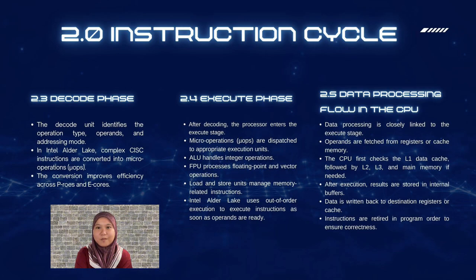After execution is complete, the resulting data is temporarily stored in internal buffers before being returned to the destination register or cache during the write back stage. Finally, the processor retires each instruction in the correct program order, committing the result to the architectural state and ensuring consistency, reliability, and correctness of program execution. This carefully coordinated data flow and execution strategy enables Intel Alder Lake processors to deliver high performance, improve energy efficiency, and stable operation across a wide range of computing workloads.